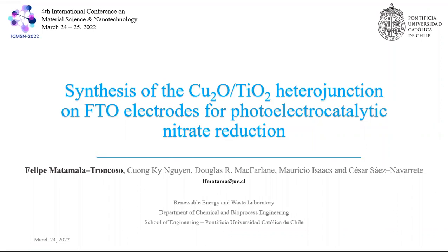I'm currently researching in the Renewable Energy Laboratory of the Department of Chemical and Bioprocess Engineering at the Universidad Católica de Chile. Our group researches the use of photosensitive surfaces to photoelectrocatalyze hydrogen carrier production. So in this opportunity, I will talk about the synthesis of a surface based on a cuprite-titanium oxide heterojunction on a transparent FTO electrode to be used in nitrate reduction.